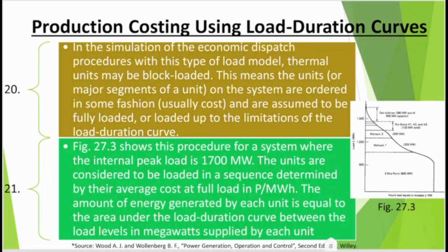In the process one can also develop an algorithm where the cost characteristic of each and every power plant is known to me, and I have the previous characteristic of load versus time. Then I can assign those generators based on the available characteristic: which power plants should be used for peak hours and which for the base loads.